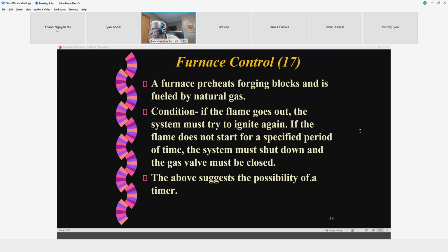unless you have a twin speed fan, which goes into a high speed when the heat has to be extracted, and then switches to a low speed when you no longer require the heat to be extracted, but you want the circulation in the house to be maintained of resident heat inside the house being pulled through the furnace even though it's not heated. Eventually, it'll start cooling down. We are going to look at some similar example. Now, modern day furnaces have become pretty complex.